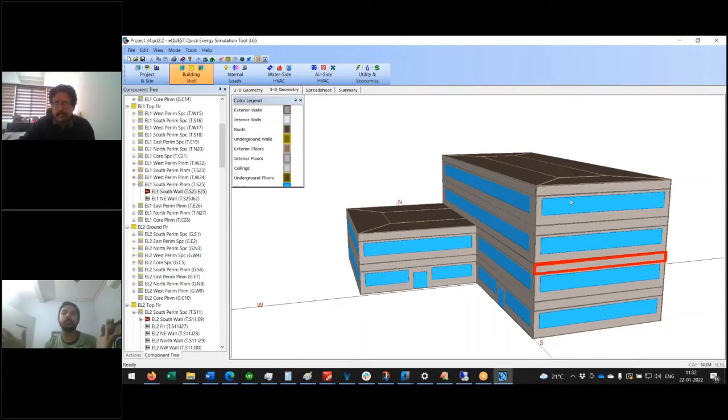So if there is a roof, it will straight away consider that it is exposed to the outer surface, outer ambience. So now the question comes, in fact, this is the next linked question, which is asked by Mr. Subramaniam, how to create a parapet wall and when you have projections. If you really want to have shades, you should model it as a shade and not as a wall or a roof or even a building.